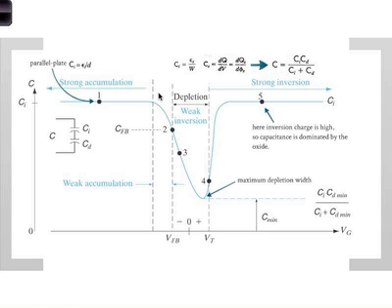Right? Why? Because you are now getting a slower reaction when you create that depletion region. The depletion is much slower than accumulation because you're pushing away the majority carriers, as opposed to already having a lot of majority carriers and having small changes in them. Okay? So one is a little bit slower than the other. So this starts becoming smaller, which means that you have to take that into account. The whole thing starts coming down a little bit.